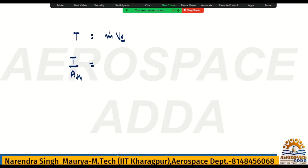Now this is very interesting question actually. So what will be the thrust per unit area? It will be the m dot divided by ATH into VE. Now this value you need to calculate, okay. How to proceed it? It's very simple. How to get that throat area and all. So first of all, you need to check that flow is choked or not. If it is choked, then maximum mass flow rate you can calculate, and in maximum mass flow rate, throat area is there, so easily you can get m dot by ATH. Okay. Before that, you have to think about the VE.